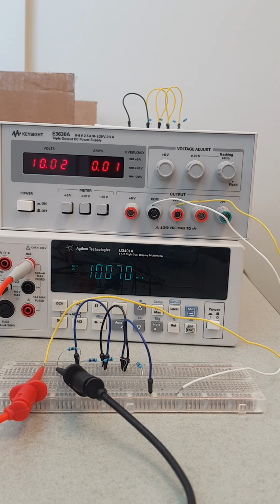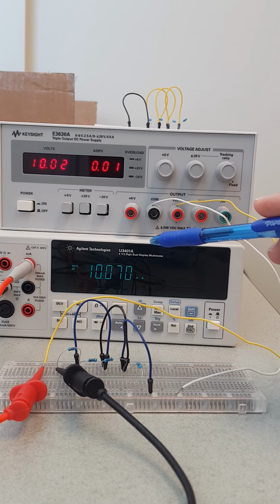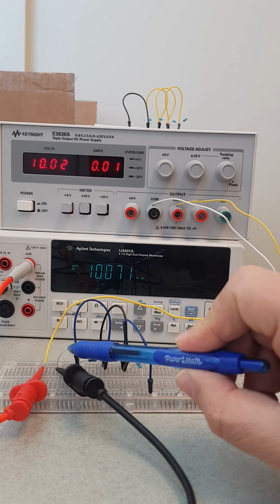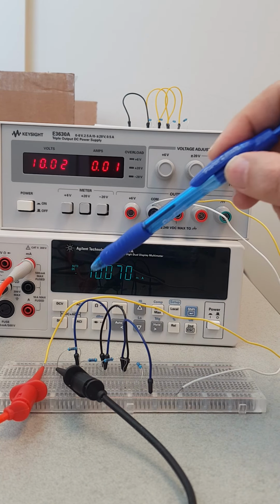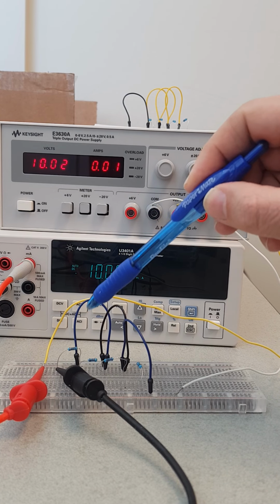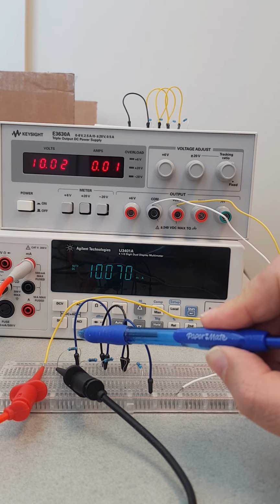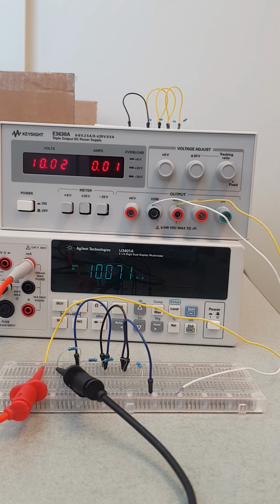So this is my circuit. We have 10 volt here, and this is the 1 kilo ohm resistance connected here. This is the ammeter connected in series with the circuit, and the rest of the resistors are short circuited. These are jumpers to short circuit them. So effectively we have only 1 kilo ohm. So 10 divided by 1, you get 10 milliamps.